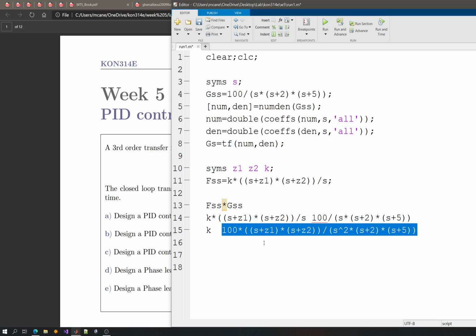So one approach is to use the root locus and examine it, and if you have a desired point, you can look at the angle condition. Let's say we have 190 degrees of an angle. Then you can say that I need a phase lag type of controller. Then I can choose this angle as 10, and then I'm choosing a suitable point.